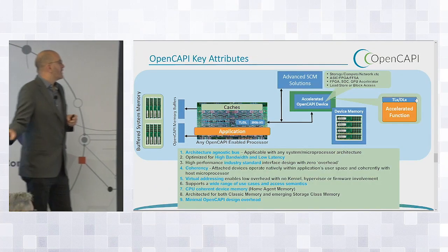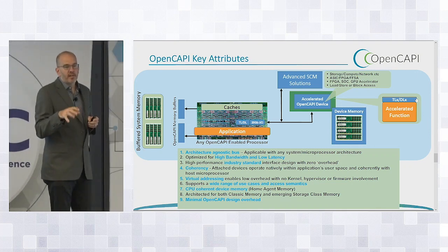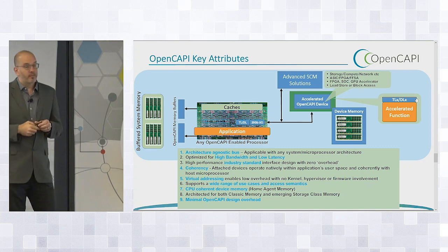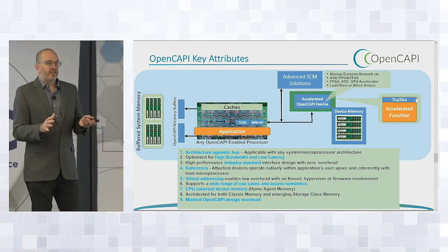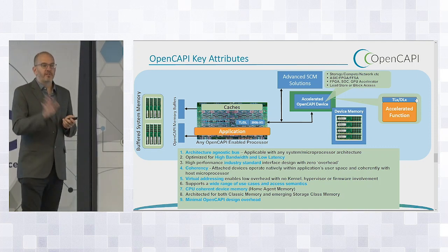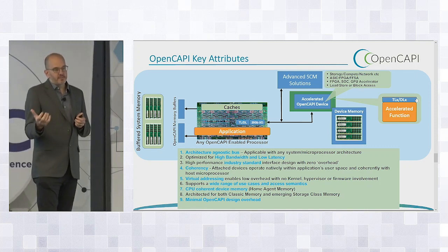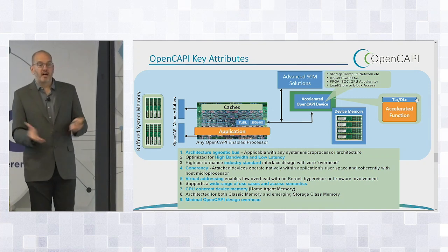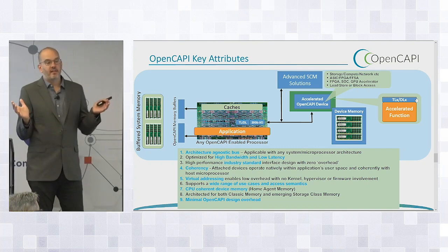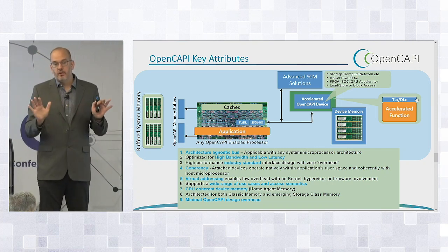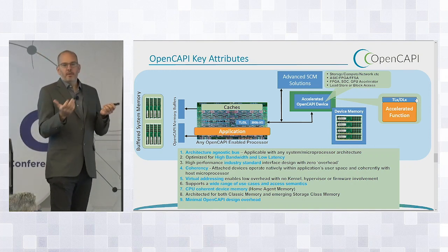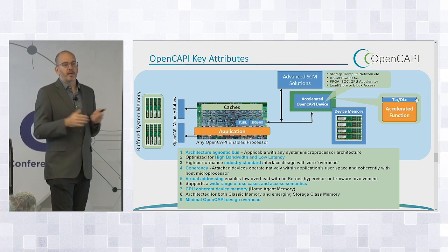So let's look at what an OpenCAPI system looks like if we think about our future. We have a derivative Power 9 system that will look just like this. Nearly all, or ideally all, of the signal IOs coming off the processor are this differential signaling. That lets us build a very composable system where maybe somebody wants to build a system with lots of DDR bandwidth, right? Some HPC lab with a bunch of codes that care only about memory bandwidth dedicates all these 25 gig signaling lanes to memory, and they have a terabyte per second of memory bandwidth.